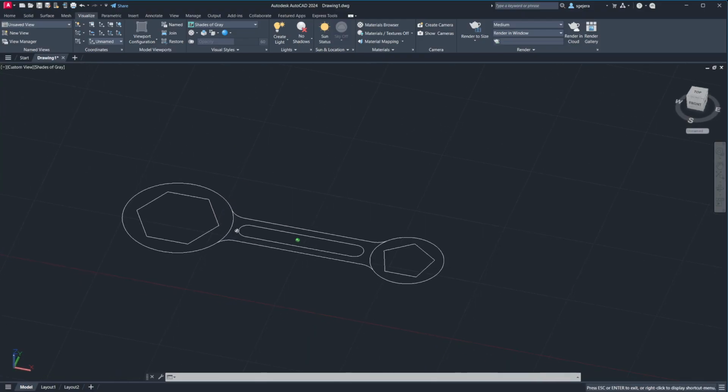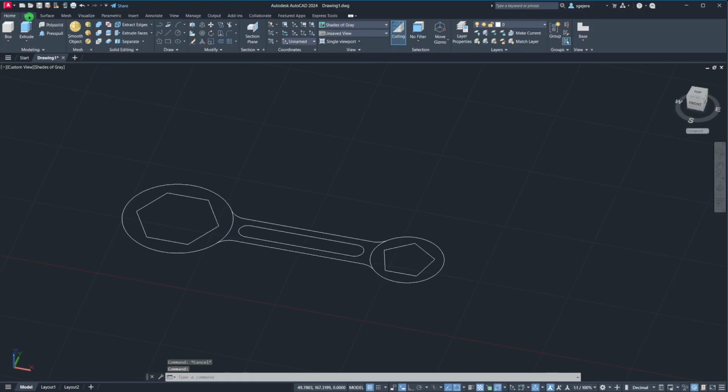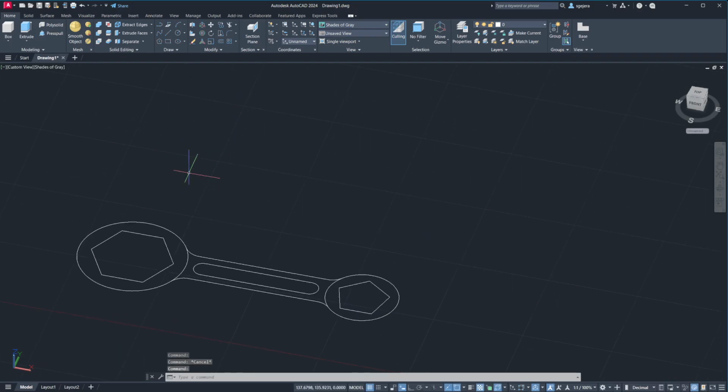So, press pull is, there are many tools to use in AutoCAD, but perhaps the number one tool that we will use is the press pull tool. Press pull is exactly how it sounds. You are pressing certain features of your object onto the object, or you are pulling those features away from the object. To illustrate, let me draw a box first.